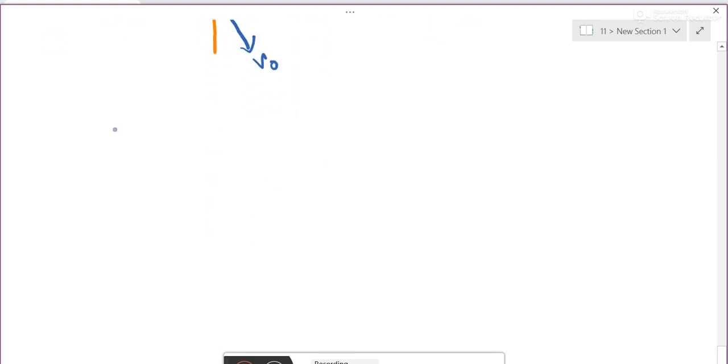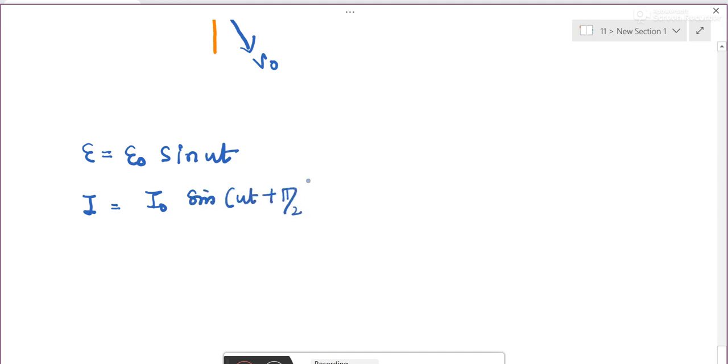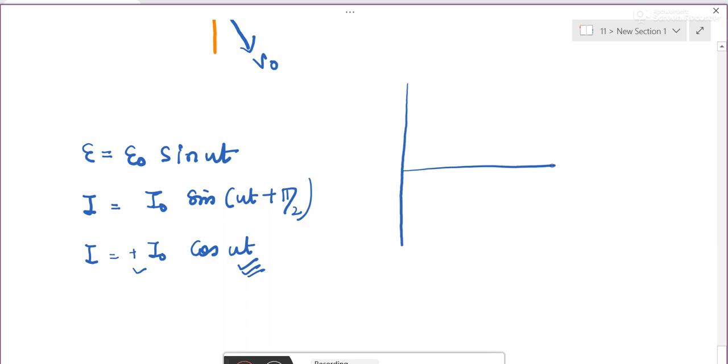And coming to the graphical presentation, for that you pick up the relationship once again. My voltage is this. So there is no problem in drawing this. I will draw a sine curve. My current is 90 degree ahead of this. So positive 90, so this was converted into positive cos only. So I naught and this is positive cos. So cos 0 is 1. So positive 1. Current will start with positive 1. So okay, let us draw the graph now. Graphical presentation.